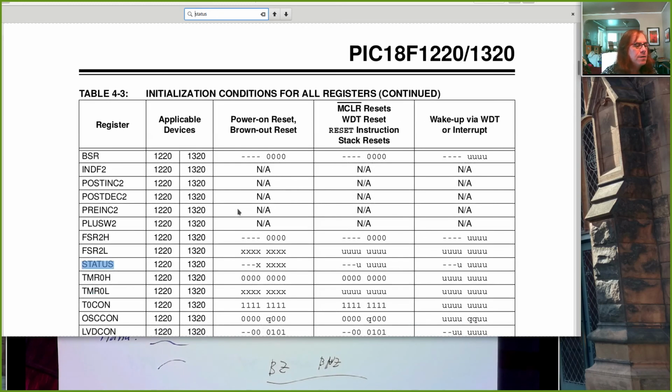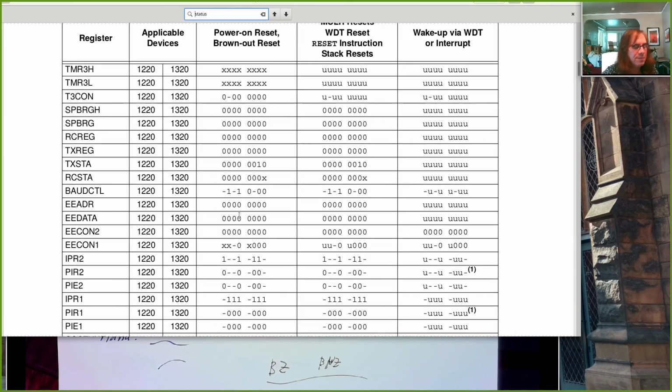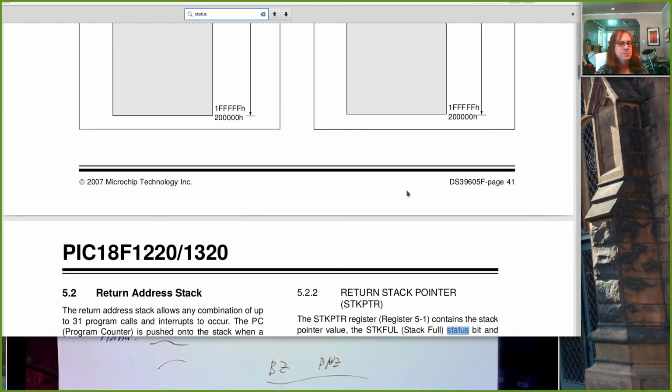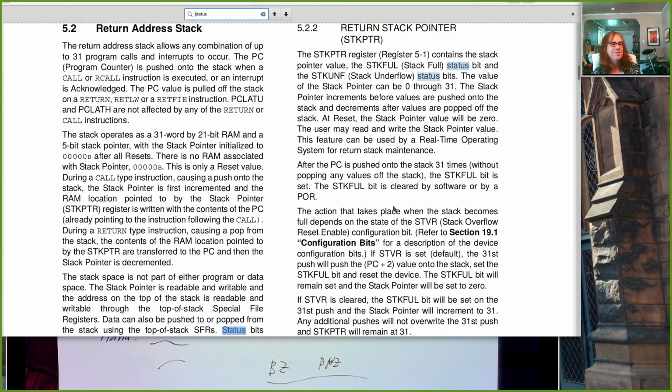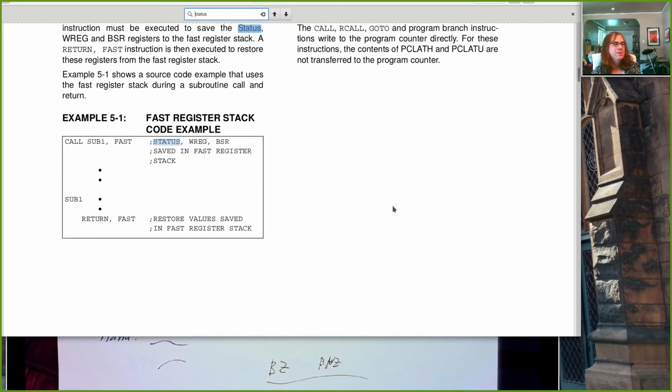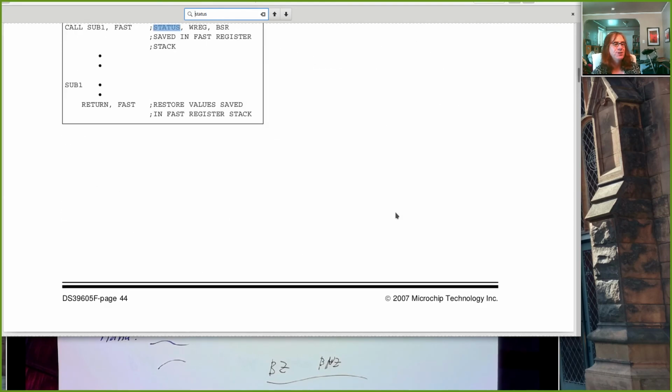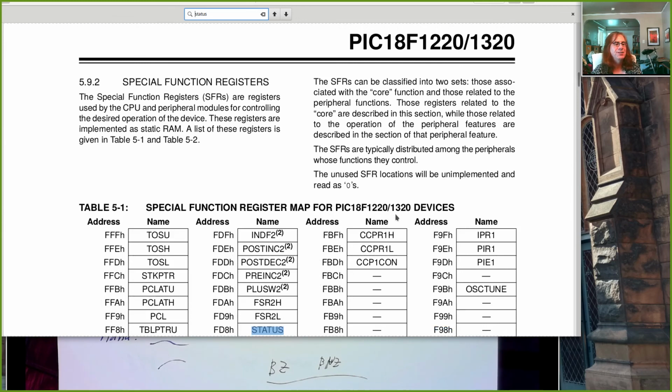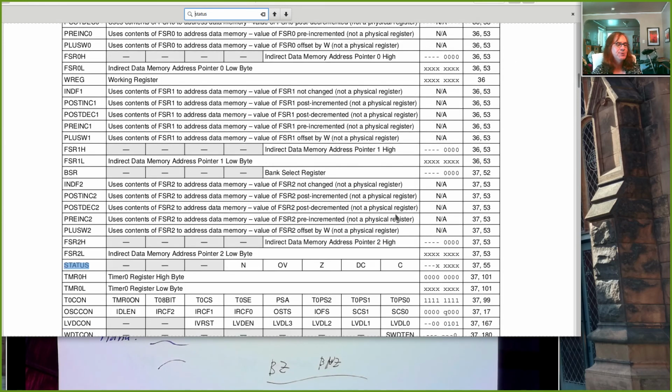Did you go in and hand manipulate them? Like if you wanted to take a literal from W and send it to the special register? Yep, you can do that. Interesting. And there's reasons to do that sometimes. For example, if you want to do a rotate with a carry, sometimes you'd like to control what that carry value is that gets loaded in.